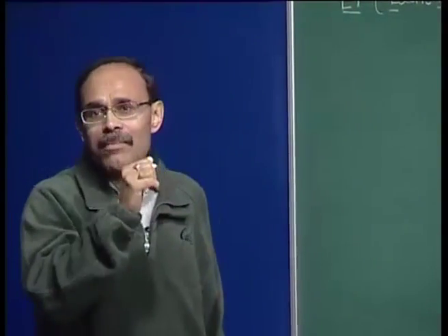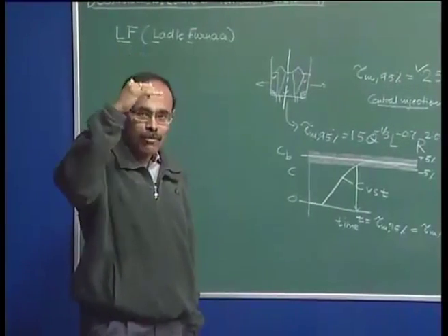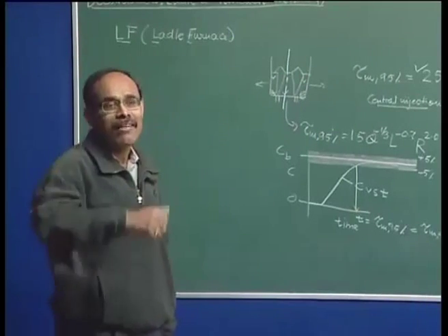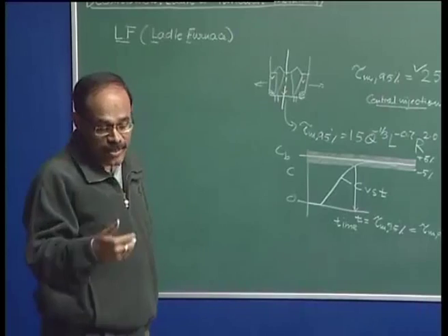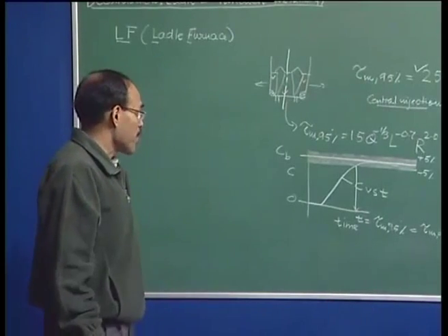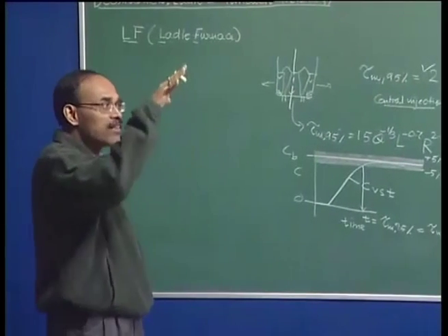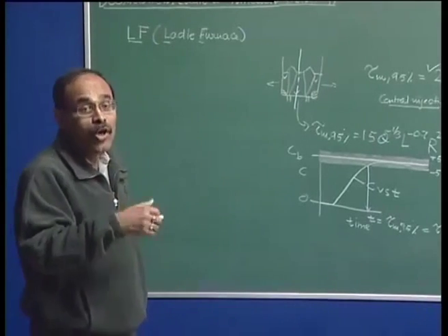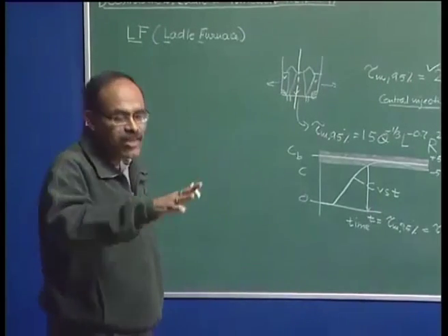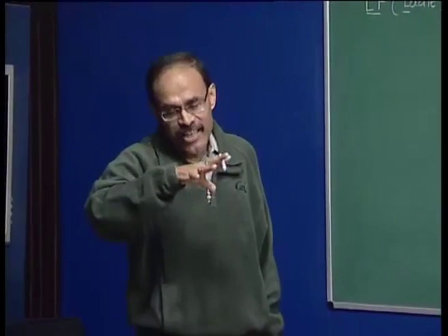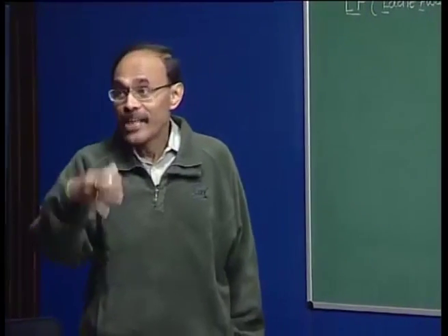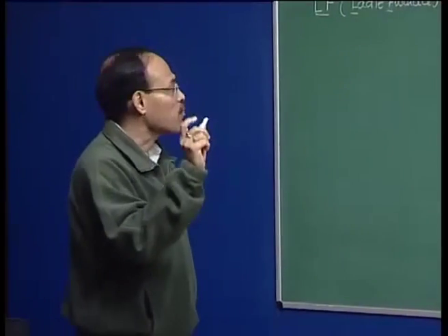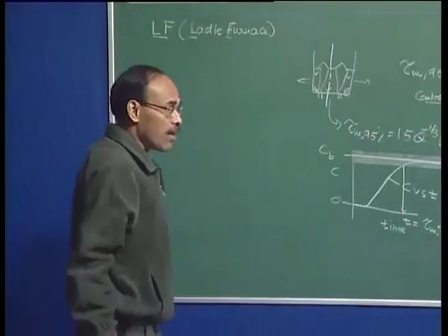So it is not desirable to increase the temperature of molten steel beyond a certain level in the oxygen steel making furnace, otherwise it impairs the efficiency of steel making. Having tapped the steel at the requisite temperature from the BOF, to sustain the entire duration of secondary steel making, we have to have heating arrangements at a certain stage, and that is facilitated by the ladle furnace.